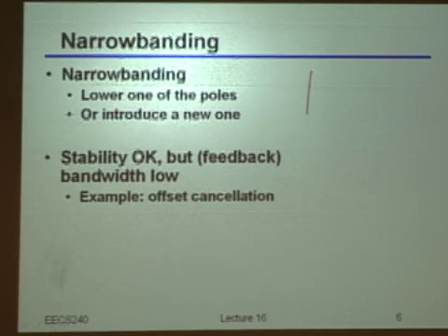If I, at the beginning, had my initial T(s), right, with two poles, P1 and P2, as I've drawn also before, the idea is I want to lower the first pole as much as possible to get the gain as I want while still having a good phase margin. So either I add another pole or I just shift the first pole as much as possible so that I already have my 20 dB per decade.